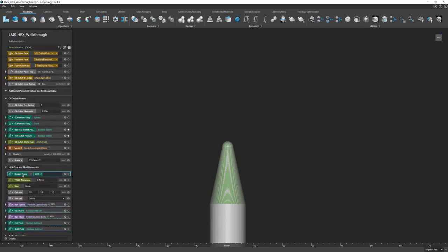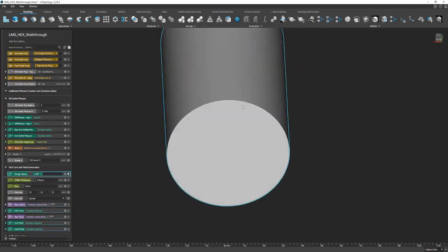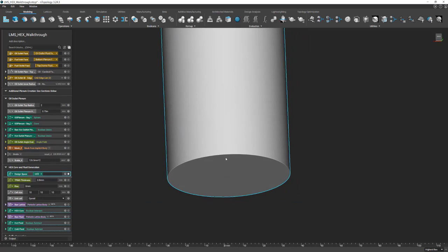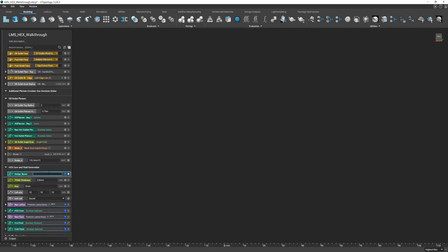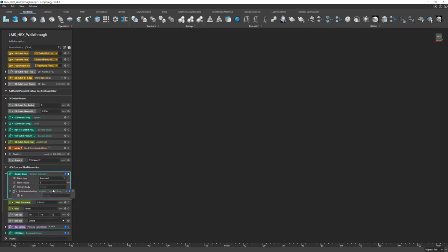So our design space in this case is our infill volume without that new plenum volume. So we'll remove this infill volume. I'm going to type in Boolean subtract here. Find the Boolean subtract, and our primary body is going to be the infill implicit, and we're going to subtract out this new hot outlet plenum.